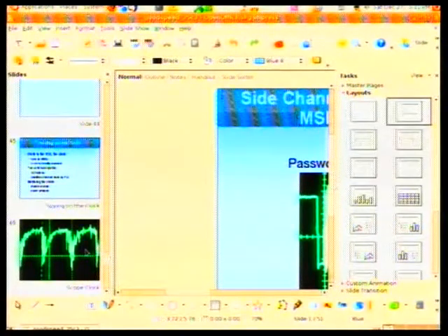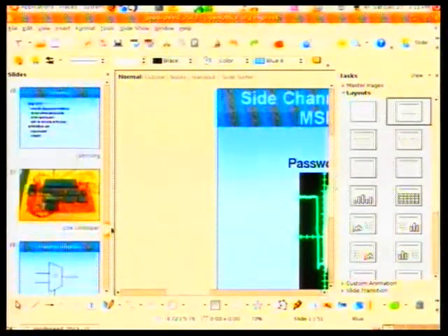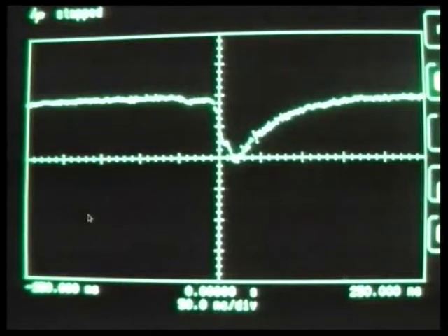How long did you say the timing glitch on the voltage rail had to be? I've had luck with about 45 nanoseconds. And you managed to generate that with the muxes and an msp430. What speed's the msp430 running at? If I jump back to the picture, no, that's not it. I'm not sure how much of this is affected by the capacitance of my probe, but you'll see that it's not a very square drop.